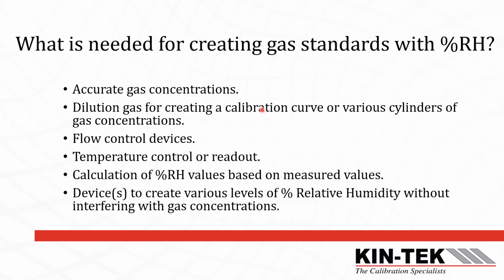So you're creating a calibration gas up here. You're actually creating your dry gas, your calibration gas, whether it be a VTEX mixture or whatever, but you're also wanting to humidify that in a percentage that is indicative of the environment in which you're working. So you have to create that percent relative humidity without interfering with the gas concentration. So those items are important and are needed for doing your calibration properly.